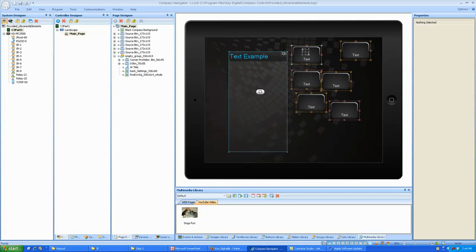We select this top left one now, and that should certainly be one of our reference points. Absolutely it is. And it should be noted, you don't have to hold shift when you're in these alignment or spacing modes, as indicated by your cursor there. You're in that mode until you exit those tools by clicking in the tree, for example. So we go ahead and we double click. We can see the properties are adjusting there, and voila, we now have this matrix alignment.